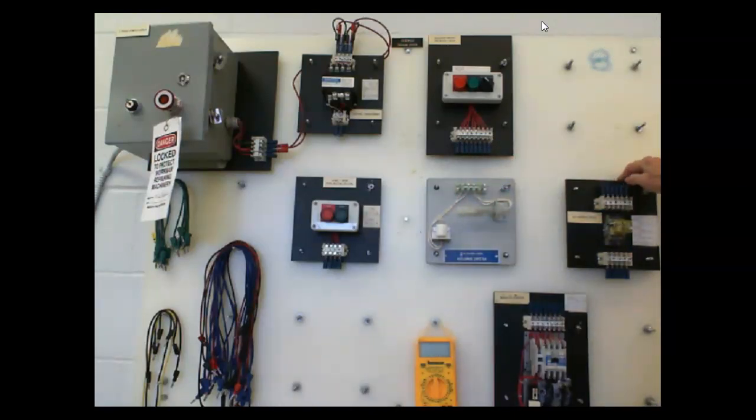Here's my control relay. The coil is 14 and 13. I'm sorry, yeah, 14 and 13. This is my coil, and then we'll be using contacts. This is a 3-pole double throw relay. We're going to be using 9 and 5. We need a normally open contact. This is my motor starter. We'll only be using the coil on this. We won't be wiring up the motor. On our input we're going to be using 10, and then our overload on the other load side is 9.